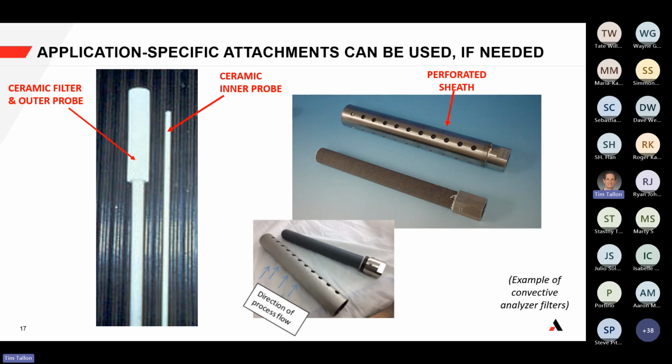There's a question about how you clean the filter, flow back or change. That's a great question. There are different ways to change the filter. The first thing is accessing the filter. There are two ways to do it, and what our service team typically recommends is, if you had a spare filter and you detected some type of plugging event, you could pull the analyzer out, or pull the probe and filter out. You could remove any plugging within the actual probe itself, remove the filter, put in the new filter, and put it back on process.